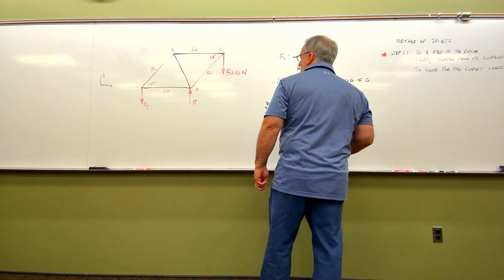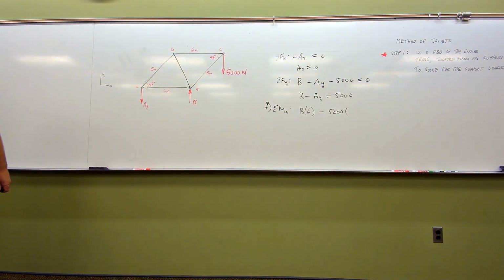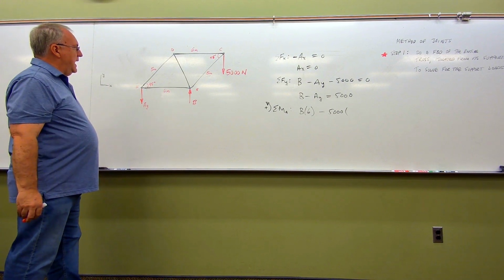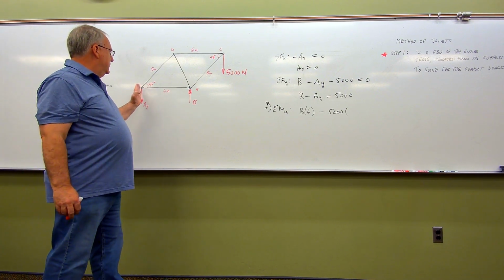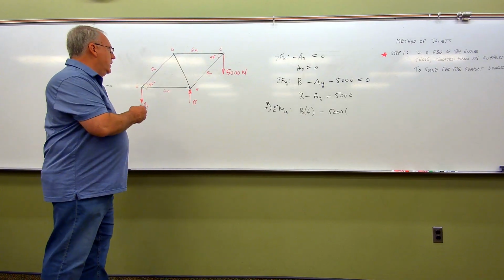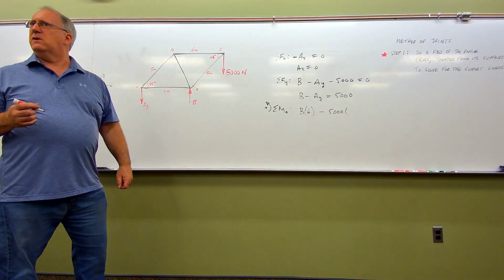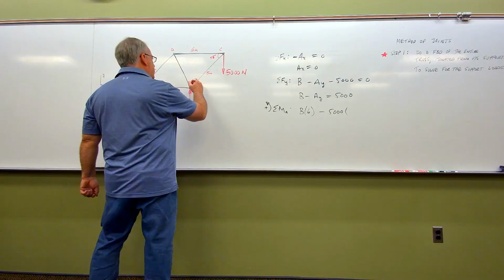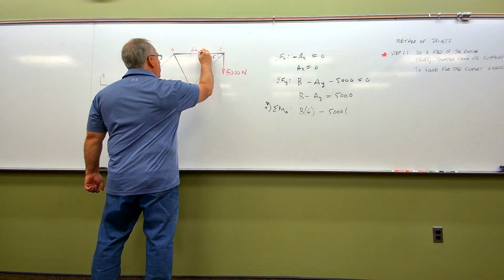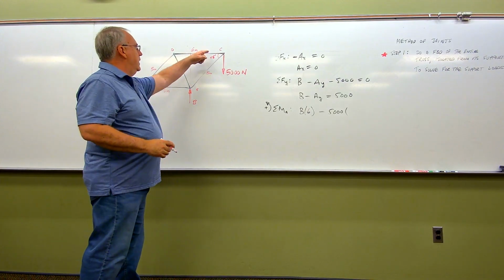And then we got to have our moment arm here. So this one gets a little bit funkier. We got to figure some stuff out here. So the moment arm, folks, is not inherently obvious. It's going to be this distance here, 6 plus this portion that I have right here. So remember, we're always looking for triangles, right? We're always looking for triangles, even when we got to draw extra triangles. So right now, if I drew in a triangle right here, I want to know this leg right here.